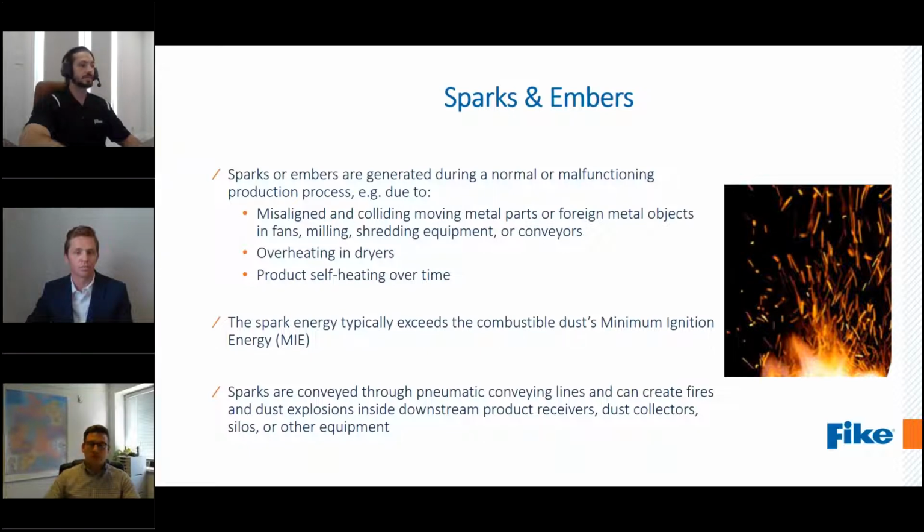And then finally, sparks are conveyed through pneumatic conveyance lines and create fires and dust explosion events downstream within other equipment that you might consider protected, but the spark is being allowed to propagate from one unit to the other.